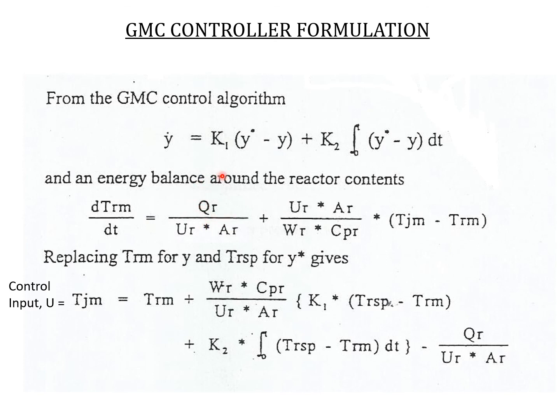So the QR is something that is dynamic. It's also changing very rapidly with time, because the whole system is a CSTR, and the CSTR depends on how much heat release there is, which makes it easy or not to control. So once you get that, we have to estimate. We have the estimator, we implement it. We measure the temperature, which we can measure, and the QR has to be estimated. Normally, as I said before, we can estimate it using the Kalman filter methods.